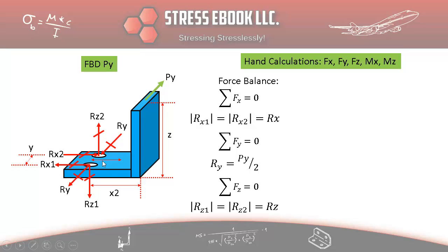Assume this is a cantilever beam, or just a beam or a rod, where you are applying this moment at the end of that rod. If you idealize this portion on the bottom and remove it and just put this moment at the edge of this rod, that's like applying a moment of Py times Z, and then you have a reaction couple, which is a moment in the opposite direction reacting this torque over here. So that's the concept here.